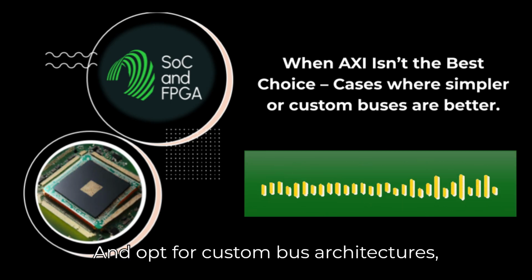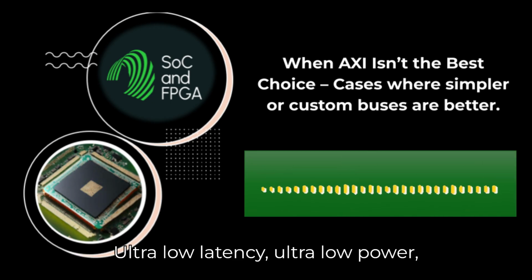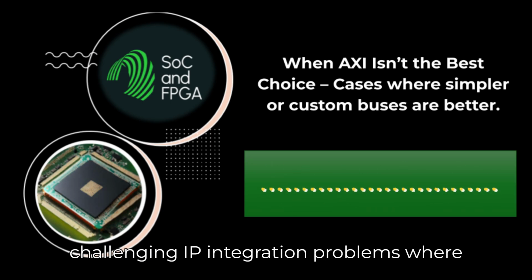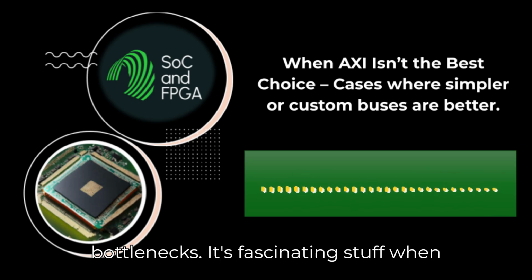And opt for custom bus architectures, whether simple handshakes, FIFOs, specialized paths, or even NoCs, when you're facing those extreme requirements. Ultra-low latency, ultra-low power, highly specialized data flows, or really challenging IP integration problems where standard solutions just create bottlenecks. It's fascinating stuff.